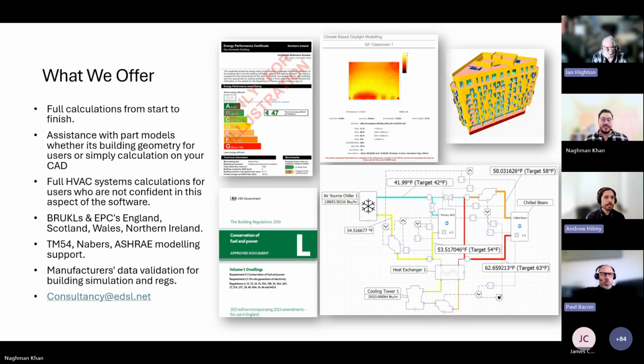You can run airside and waterside reports as well, can't you? And all the numbers are in there, so if anything looks strange in there, that's a good starting point. Yeah, the reports are good. There's frequency reports as well. So again, if you wanted to look at something that wasn't just unmet hours, for example, if you expected a certain component to behave in a certain way, then you could run the frequency report, and that would give you an idea as to whether it's behaving as you expect.